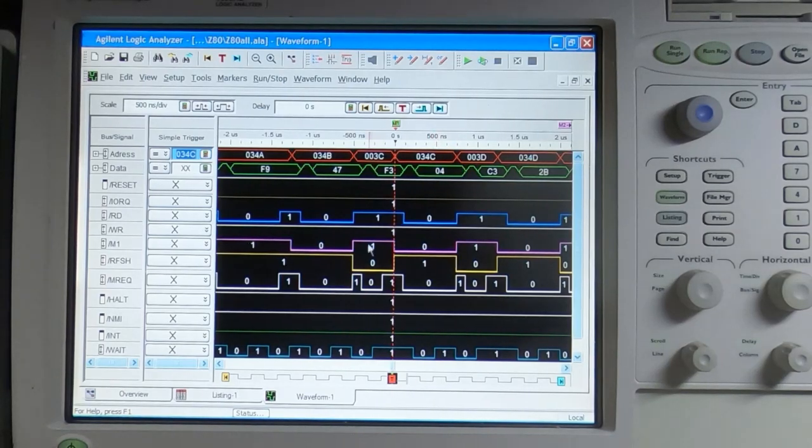That's here. Remember that the refresh cycles are also running here, so it's dynamic RAM, of course, so you need to bear in mind that the intermediate values we're seeing that are counting up are doing that because they are the refresh cycle values. So here it's saying 3C, 3D. These are two refresh cycles, so don't be misled by those. Just ignore those for now.